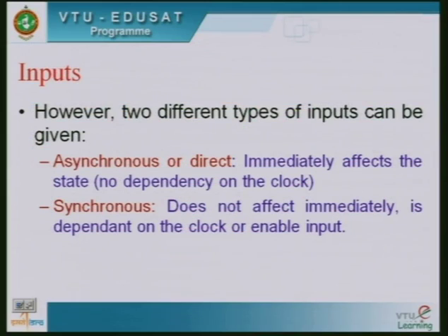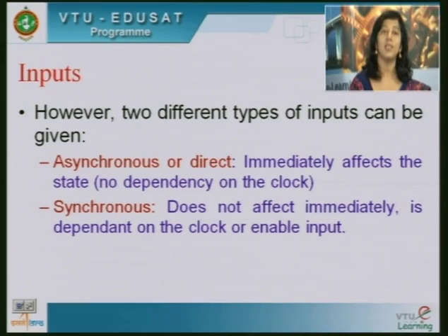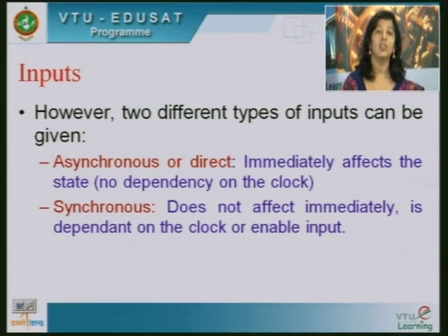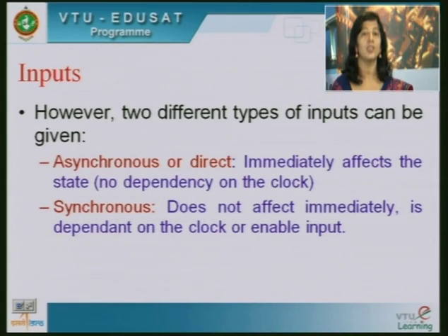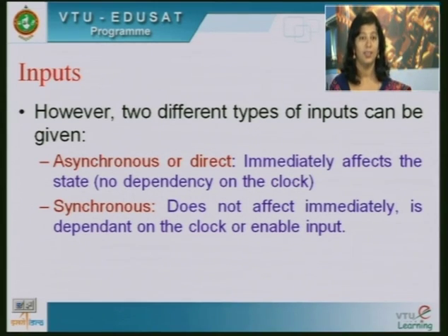So, I can add inputs in two ways, either asynchronously or directly, and the other way is synchronous inputs. So, when I add asynchronous inputs, it means irrespective of the enable or clock signal, those inputs will change the outputs. So, the inputs affect the outputs without any clock signal affecting it,